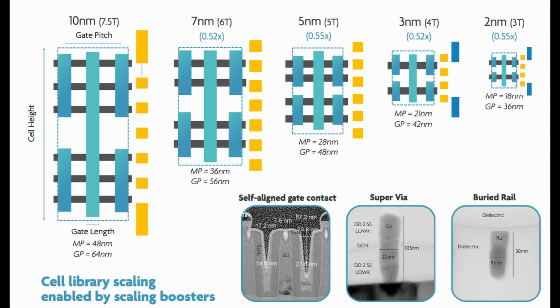At the beginning of FinFETs, designs with 4 or even more fins were the standard. Nowadays, even 3-fin cells are usually reserved for high-performance cells, while 2-fin designs are becoming the new standard. And 1-fin cells are not too far away. That's why recent FinFET process nodes still offer a decent increase in transistor density. Because once the traditional scaling of FinFETs slowed down, the foundries started to reduce the amount of fins used in their standard cell libraries.